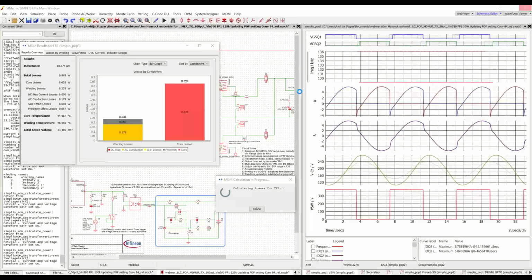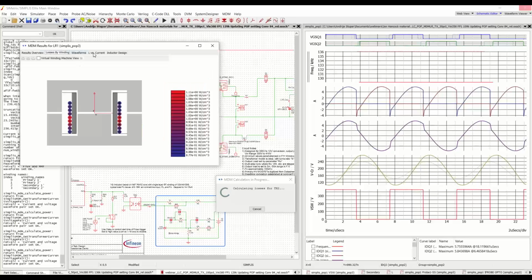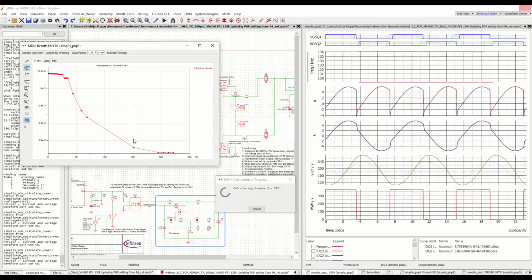And then based on that, we calculate the total reluctance of the core. And then, of course, using the number of turns, we calculate the inductance. So we use the initial permeability of the material defined in the database to get that one number, which is displayed here. But then we use BH curves or μH curves or whatever happens to be available for that material to calculate this L versus current plot.